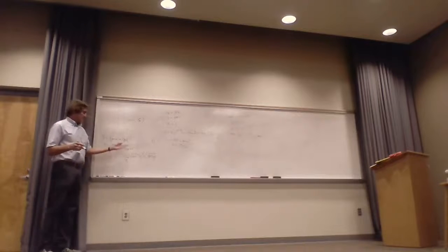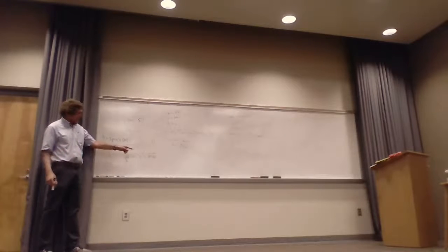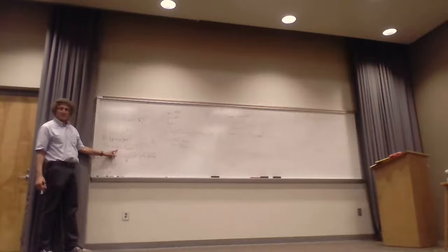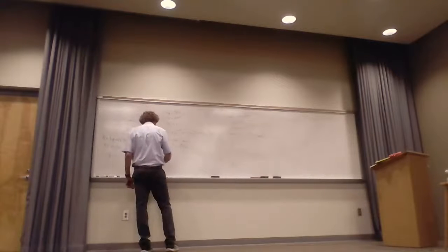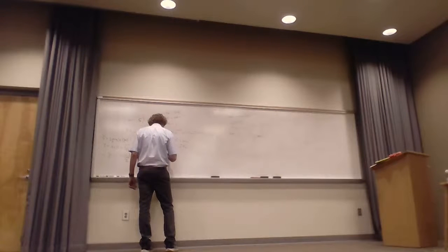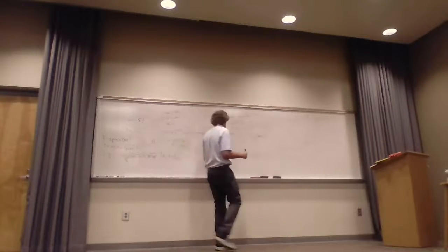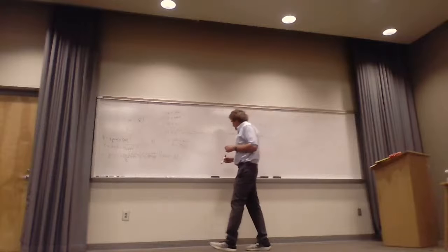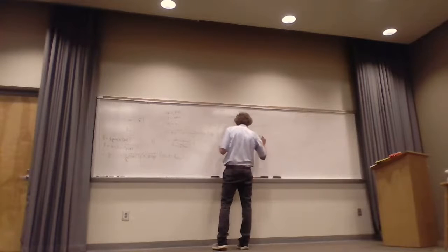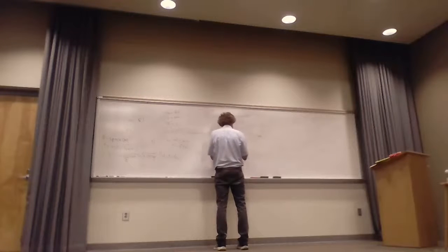And what can you glean from this? By looking at it, you see how alpha and beta have to be the same. Y'all with me on that? Because that's critical. So here I know that alpha equals beta, which is equal to the square root of pi f mu sigma, right? And now that I've got that, I can get whatever I want. I've got those two quantities, and the question for part A was the intrinsic impedance.